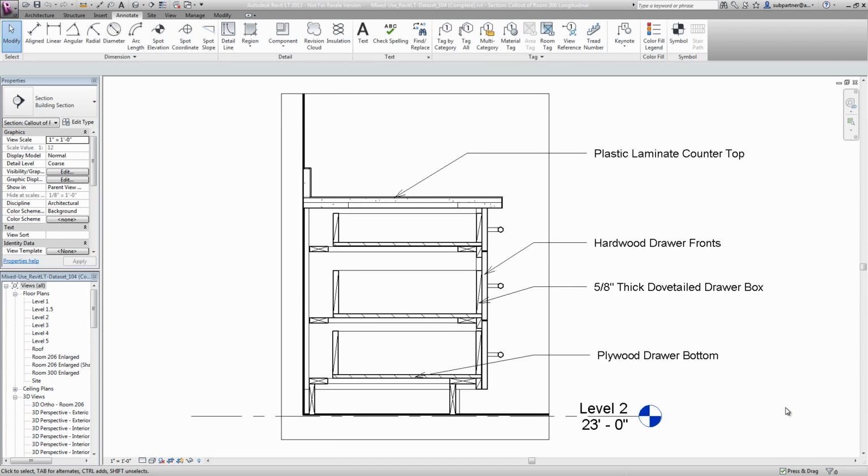There are a few distinct advantages to creating such hybrid details. First, you leverage as much of the model as practical so that you don't waste time redrawing. Next, your detail will be more accurate since it's being drawn directly on top of a live model. If the underlying model changes, you'll be able to react to those changes directly in the detail, and in some cases, the 2D elements will even stay attached to the underlying 3D geometry and update themselves. And finally, callouts can be placed directly on sheets, and all annotation and tags are fully coordinated.